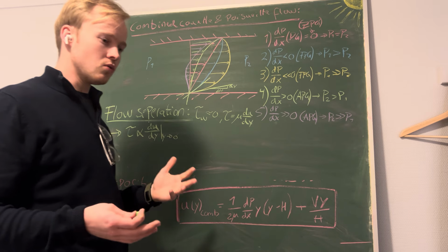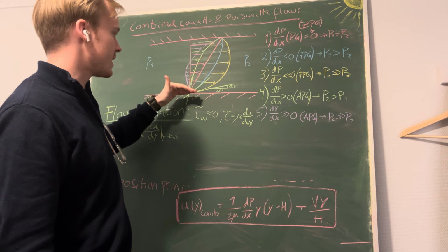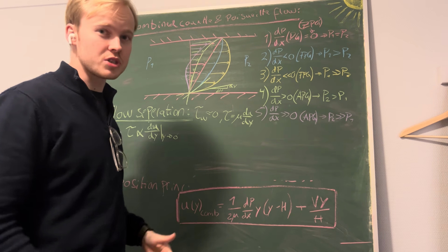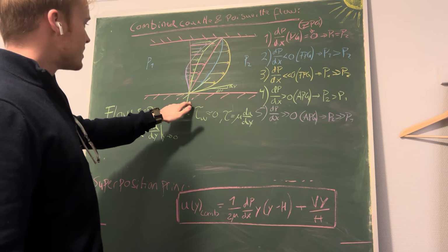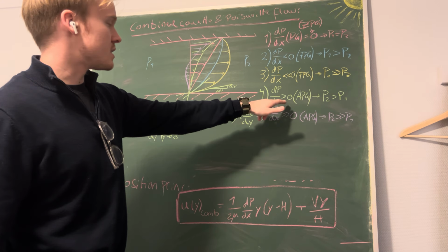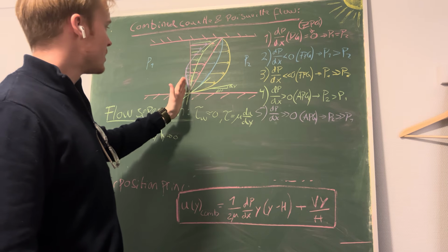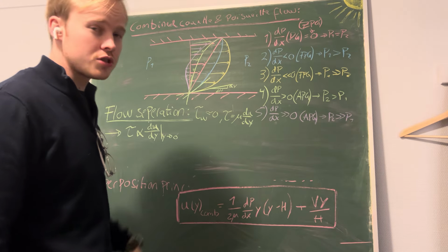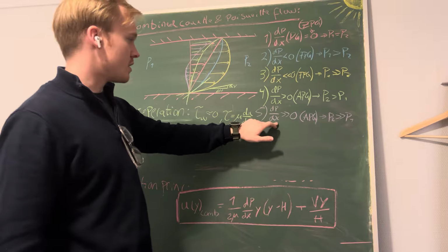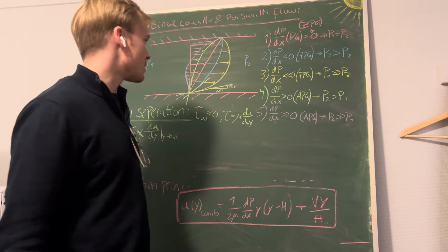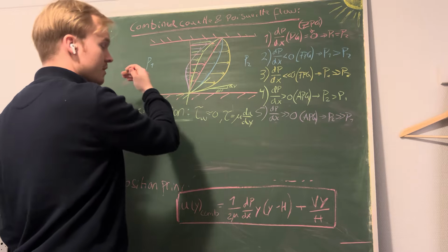That means that there is no force holding our velocity profile connected to the surface, which means that it's going to slip or separate. So even in this case, when dp/dx is larger than 0, given this value, it is on the verge of separating. And in this purple case, when we have a very big adverse pressure gradient, we definitely have flow separation because we have backflow.